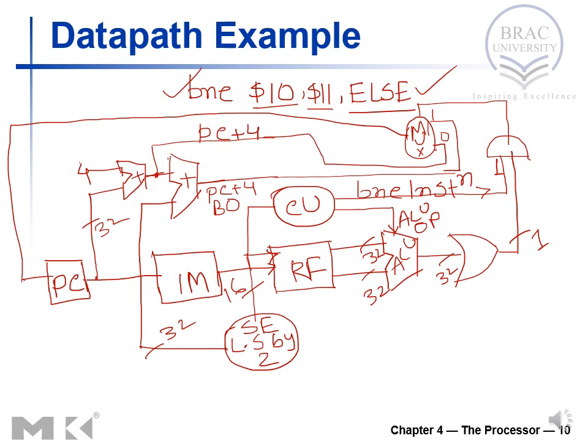Now see what is happening inside the ALU. This link carries data coming from register 10, and this link carries data coming from register 11. If both the data are equal, then their subtraction would be 0, which means the ALU will output 32-bit zeros.